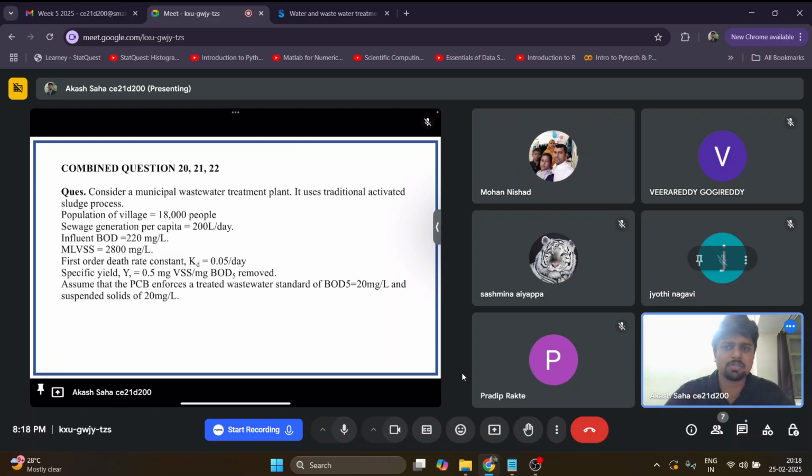Yeah, volume upon flow, that is true. So for flow, take population into per day, 8,000 into 200. Yes, that is true. And that gives us the flow. Volume is 325, it's given in the question. So just divide it and tell me what the answer is. Just make note of the units. It should not be in days, it should be in hours.